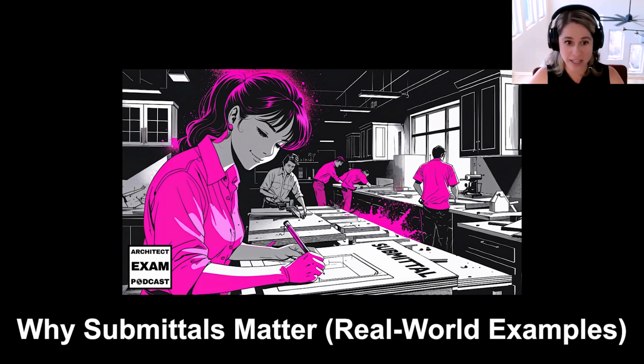And this was a 3-story lobby, and repainting it was not an easy task. It actually delayed the project close out by 2 weeks, and it cost an additional, I think it was like $20,000 to $30,000. So really a simple paint sample and a paint submittal review process would have prevented this entire issue. It prevents installers from just making their best guess to go ahead and install an item and keep the project moving. The submittal process is really checks and balances throughout the construction process to make sure it is ultimately what the owner wants for the final completed project.